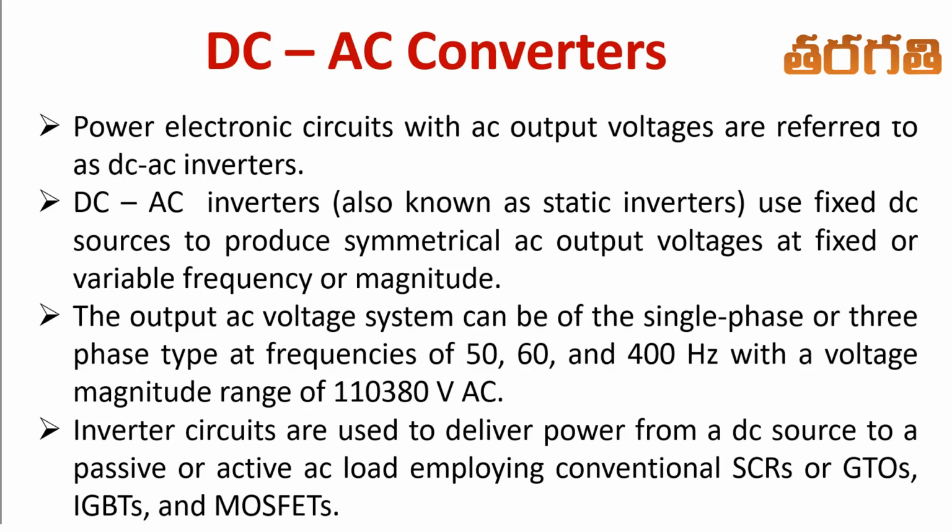To turn off the SCR, whenever it is required to bring the thyristor or SCR into off state, a separate turn-off process is needed. Whereas the advantage with using GTOs is that whenever you are required to turn off the switch or bring the switch into off state, by that moment you can remove the trigger pulse. That means by applying a simple trigger pulse, injecting a pulse into the gate circuit, the thyristor or the GTO can be brought into off state.